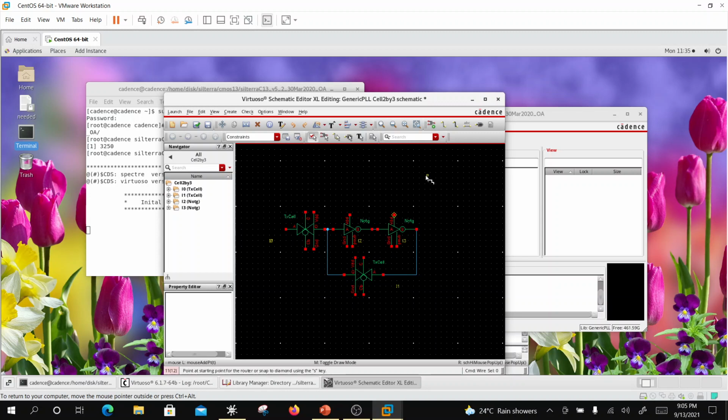Okay, so that is a latch. And I will connect these in tandem. So C would be connected with C bar over here, and C bar is connected with C. And then you can run all the grounds together.